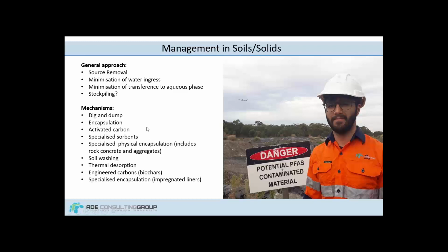Activated carbon amendments in soil is another one that's been practiced. Activated carbon does have its place. However, reading through literature, I'm aware that it does have some limitations around short chain PFAS. And when we talk about sorbents, we really need to discuss how reversible is the sorption of PFAS to that matrix, rather than just looking at things like surface area and iodine number, which in themselves don't tell us a lot about how strong the sorption is and to what extent it takes place.